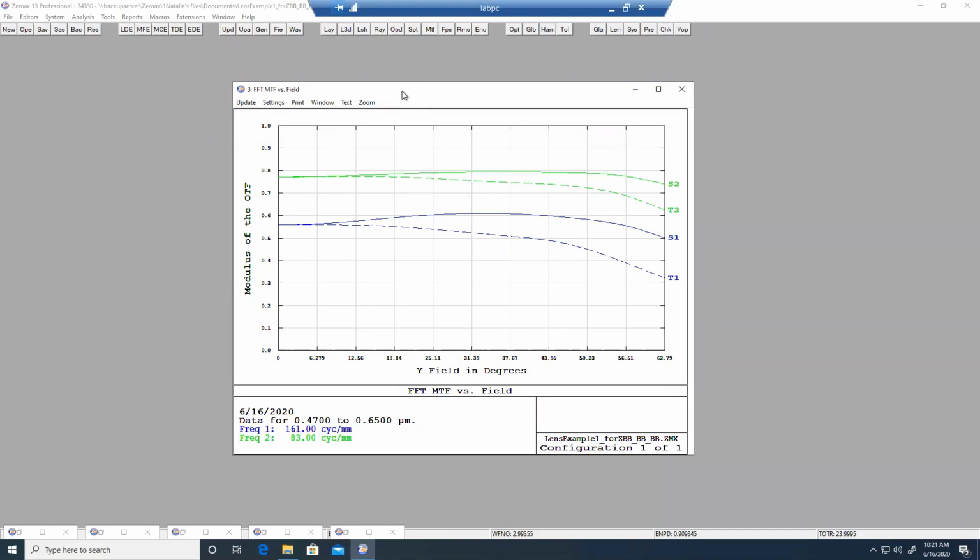Right. So exactly, these are the different spatial frequencies. The spatial frequency that is being used to evaluate a lens system really depends on the sensor and the pixel size that is being used. So every sensor has what's called a Nyquist limit, which is the limiting resolution of a sensor. Through a mathematical equation, this is a direct correlation to the pixel size.